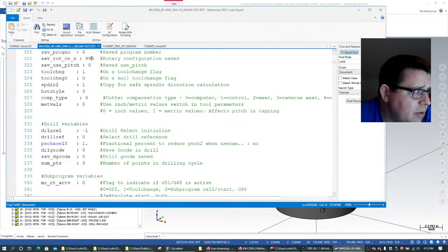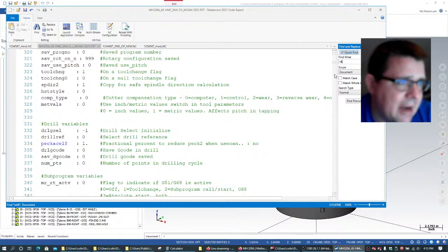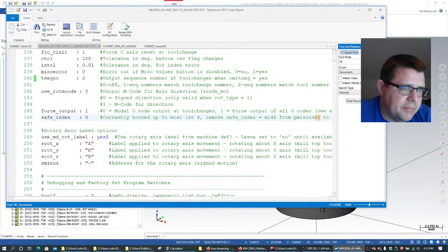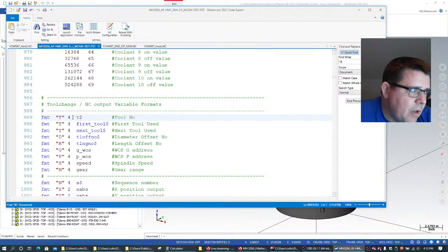So first thing I'm going to do, I'm going to go to my post processor and find my formatting for $. Right now, the tool numbers are set as integer. So this is the format for my tool. This says, this is the variable, $. This is the number that gets applied to the variable. And then this is the string in front.